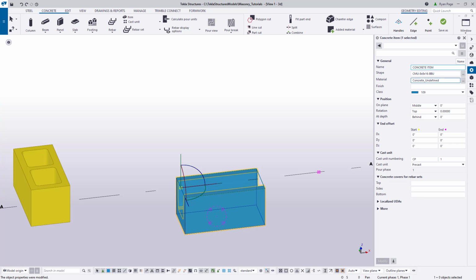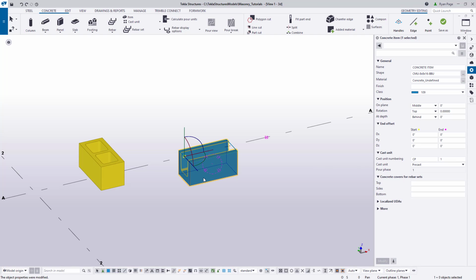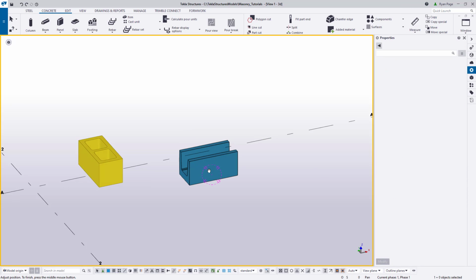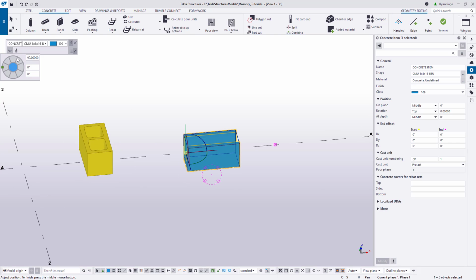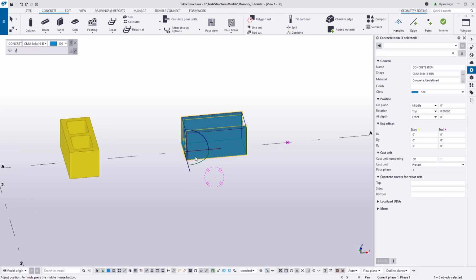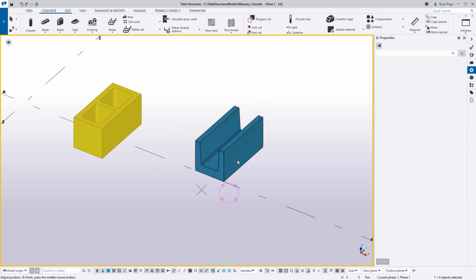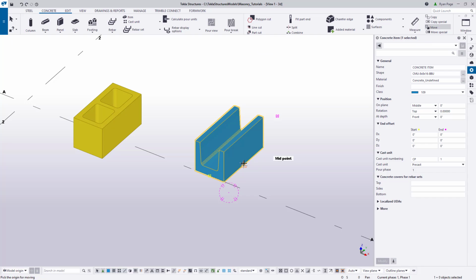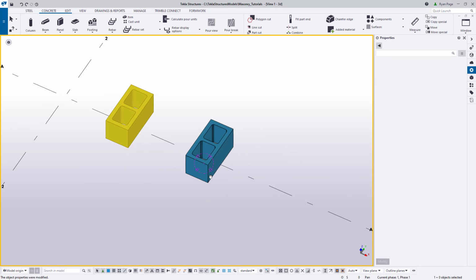So it's pretty easy, as you can see, to kind of utilize items in the pre-existing shapes. No matter what we do with our grips or how we model them, they're going to be in the orientation dictated by the shape. It's easy to kind of change the position. We can rotate around the insertion points or the block in and of itself if we do need to manipulate that kind of stuff. But it's a lot easier to maintain and manage these items, and it's a lot less on our system resources. So although this example is pretty basic, it does prove the points on why there's some efficiency and benefits to using items and shapes for our masonry units. And as we get into the masonry tools themselves, you'll be able to see the benefits even further.